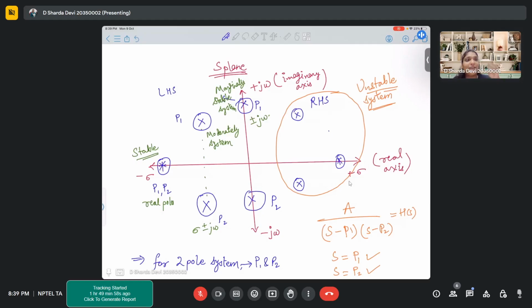But where the poles are, based on that you will get the phases, and from there you will calculate the phase margin, and you might come across that the phase margin is going beyond 180 degrees. So the system has already become unstable. All the poles are in the left hand side, but still the phase margin has gone beyond your 180 degrees, which is the limit. So that will introduce instability. So that is also possible.